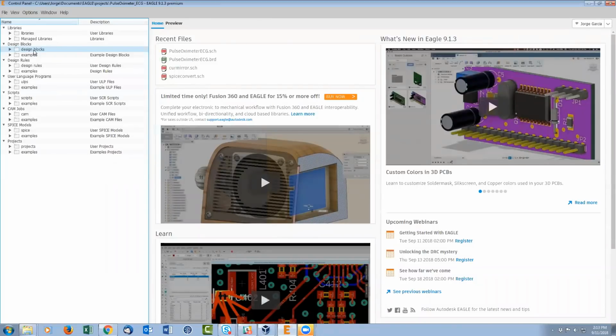Just as a really straightforward example, if you work in audio, let's say you're a pedal manufacturer, there's certain parts that are going to be the same for every design. You're going to have the same switch, the same input circuitry, same output circuitry. The magic happens in the middle. So you can make the switch, the input section, the output section, you can make those a design block. And when you go to design your next pedal, you just bring it in.